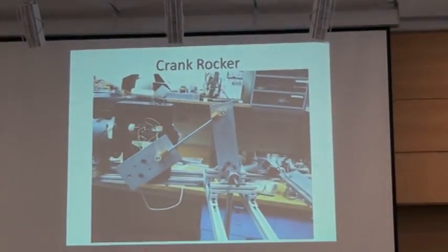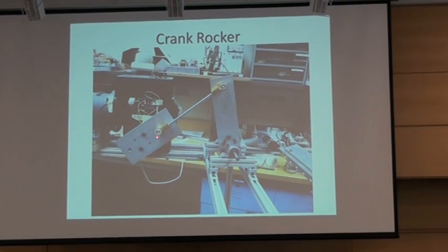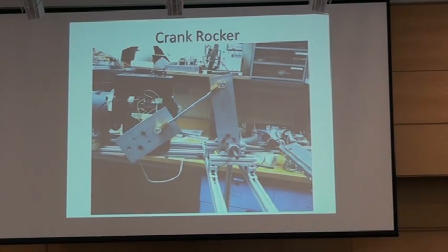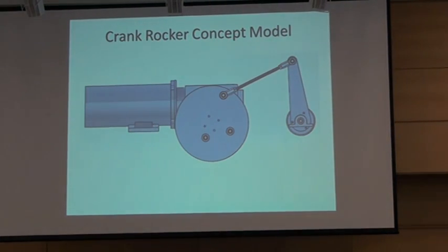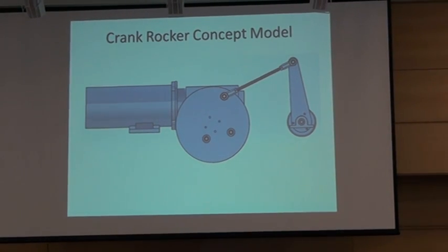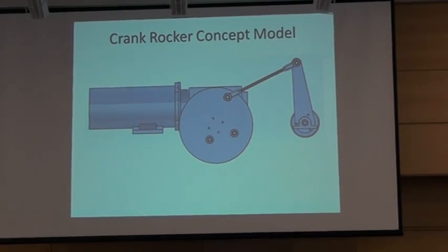Yeah, these golden pieces up here are the ball joints, and on the back side of that is a nut. And you just unscrew that nut, and you remove the ball joint from the crank, and then you just put it into a different angle hole and screw it back on, and you're ready to go.